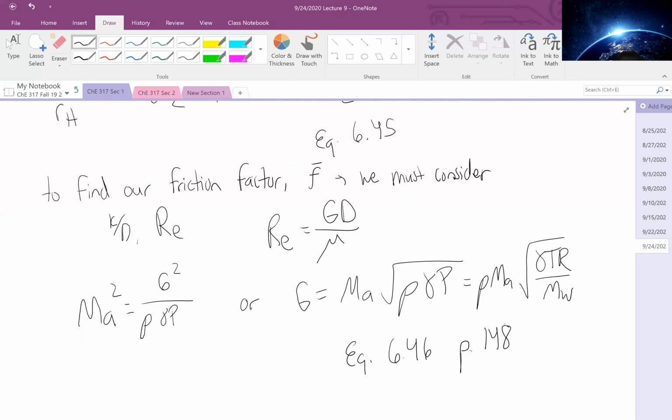You can follow a similar structure for compressible flow. However, getting to some of these values is a little less obvious, particularly as it comes to having to rely on mass velocity, because density and velocity will fluctuate throughout the entire system.